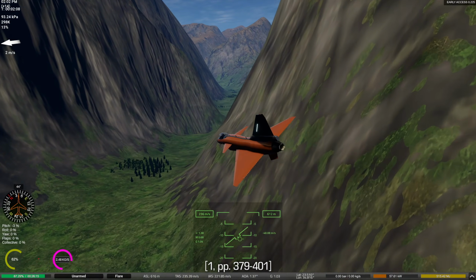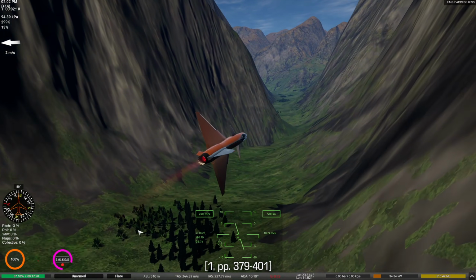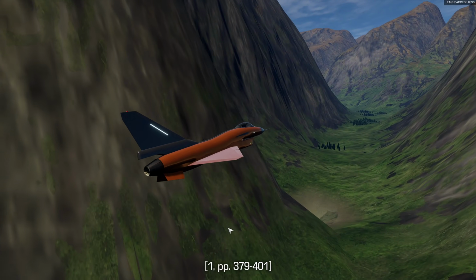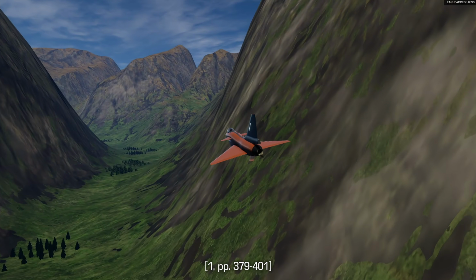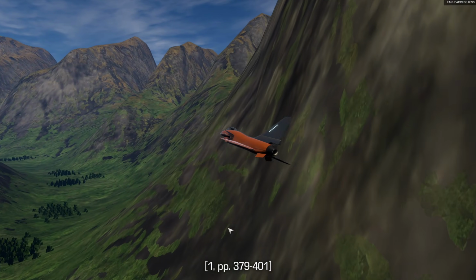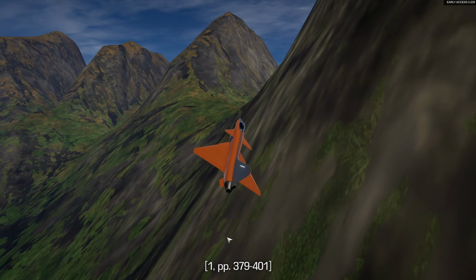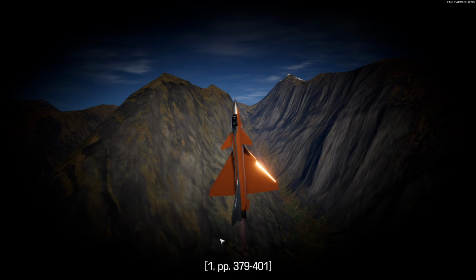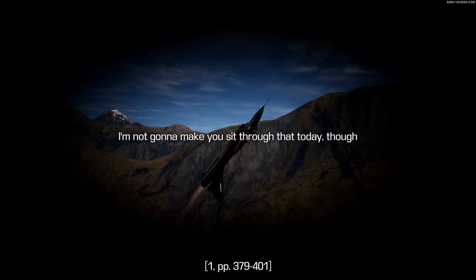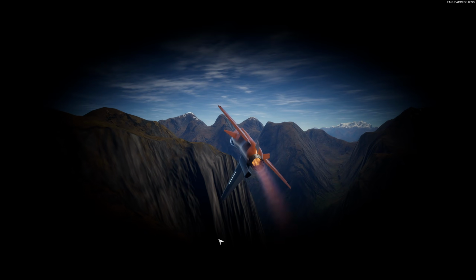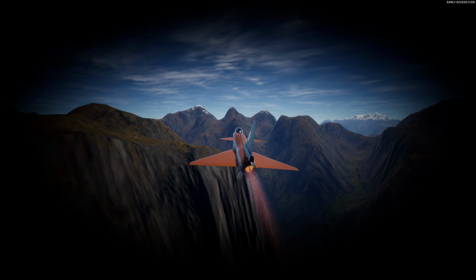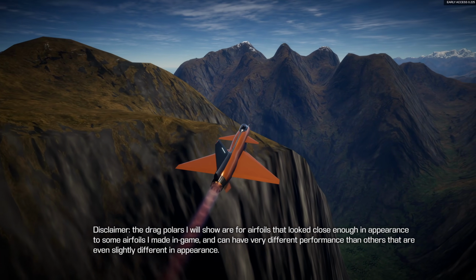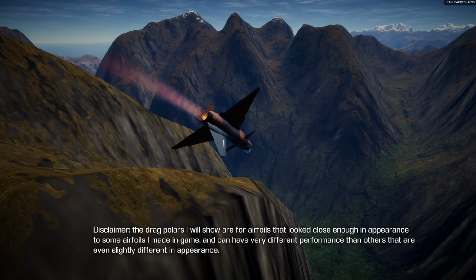Returning to airfoil drag, there are no nice and simple approximations to estimate total drag the same way there are for lift. Additionally, the drag coefficient is generally very sensitive to multiple factors, such as whether the flow is separated or attached, turbulent or laminar, and so on and so forth. It is at least possible to obtain a somewhat reasonable estimate for skin friction drag by using equations for that of a flat plate. We can, however, compare data from Flyout for airfoils with varying thickness to that of real airfoil drag polars, where a drag polar is a plot of the drag coefficient per a given lift coefficient.